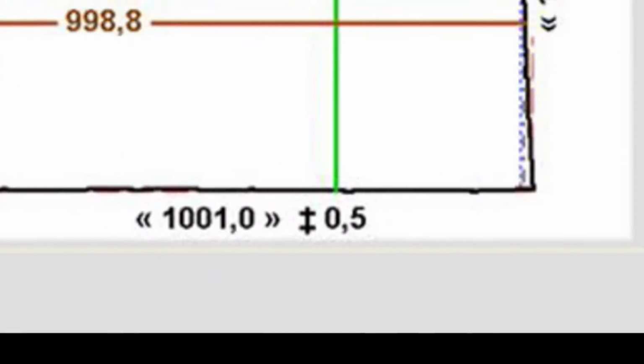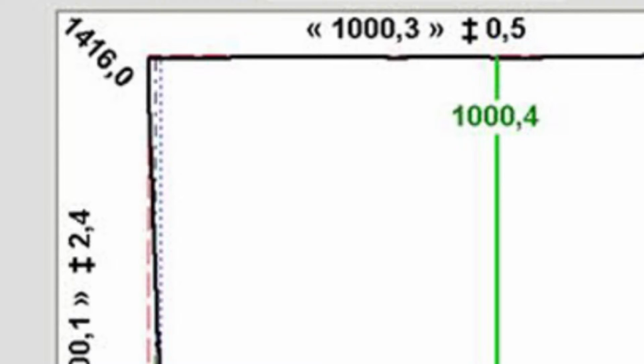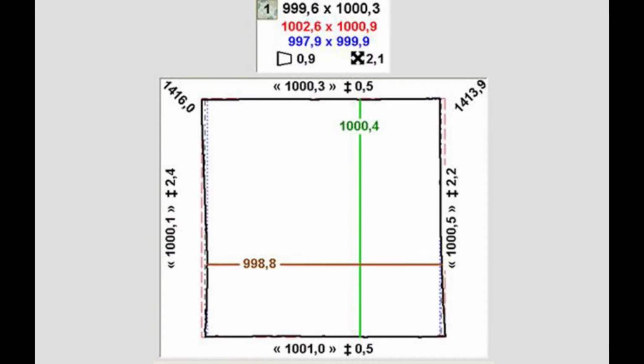In graphical mode, we can see the layout of the outside of the tile, maximizing defects, so we appreciate them well. Two frames are added to this path. One of maximum external dimensions, and another of minimum interior dimensions. It allows us to observe possible trends in the tile. If it is deemed necessary, an internal cursor, showing us the actual dimensions at the point we want, in order to quantify defects, can also be activated.